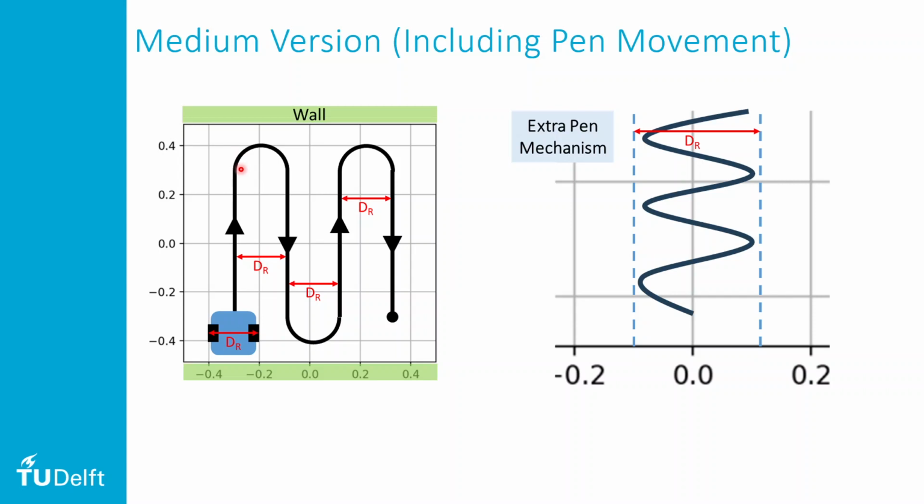Right. So we drive straight, we see the wall. When we do, we trigger the turn. We turn hopefully exactly 180 degrees. Then we drive straight again. When we see the wall, we're going to turn, but note that this time we need to turn to the left instead of to the right. So we do that. Then we go straight, see the wall, turn to the right again, straight, and the fourth time we see the wall, we don't turn, we stop. And ideally, I can't remember if I said this is a requirement or not, but we should then go back to the wait state so that we could start that whole process again.